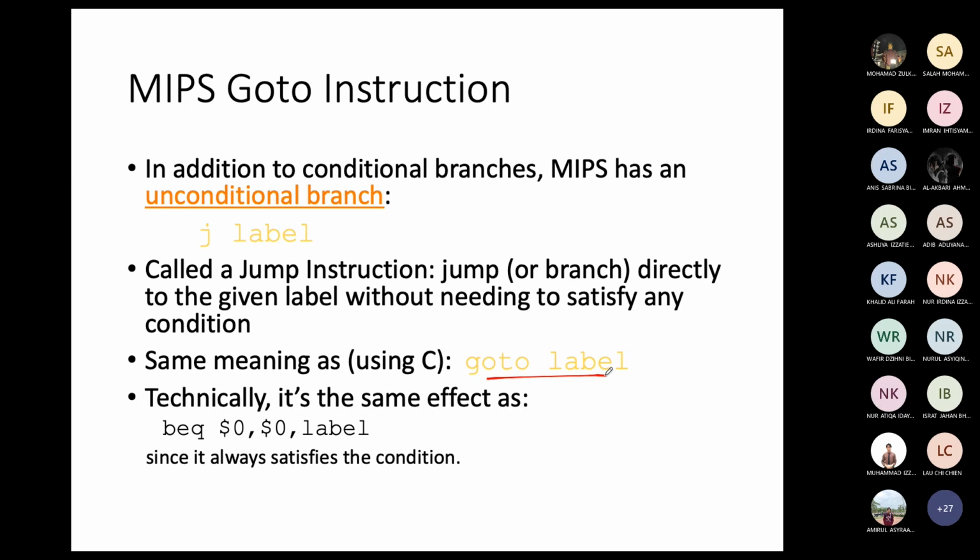Technically, it has the same effect as BEQ, which means: is register 0 equal to register 0? We jump to label. Since it always satisfies the condition, because 0 is equal to 0, yes, we just jump.